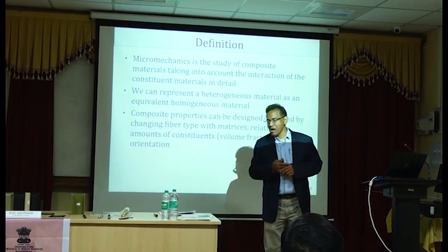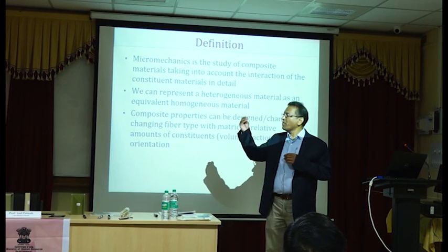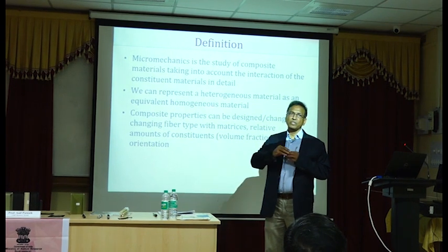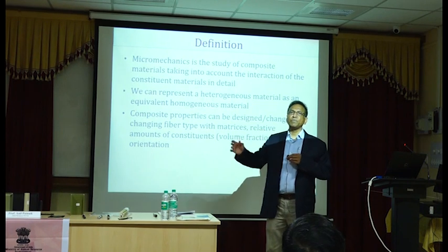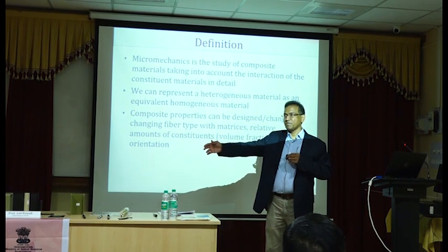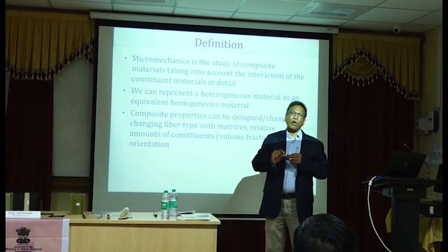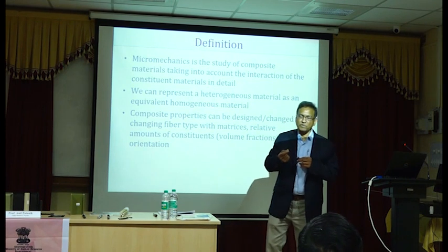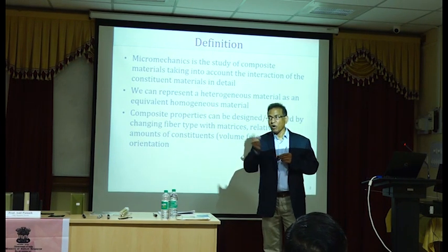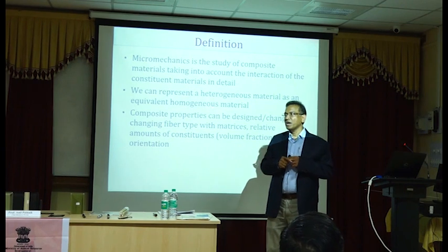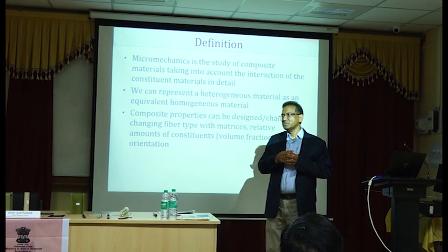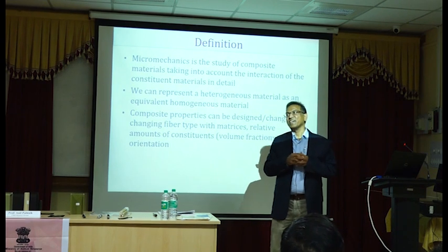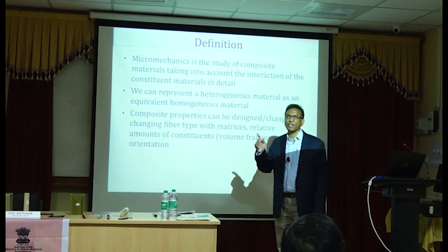So if you have a larger amount of fiber, you will have mechanical properties of the composite that are more similar to the mechanical properties of the fiber. But if you have a very small amount of fiber, let's say 5% by volume, I am assuming it's by volume. If it is by weight, it's different. By weight, okay, that's the reason you are saying 70%.